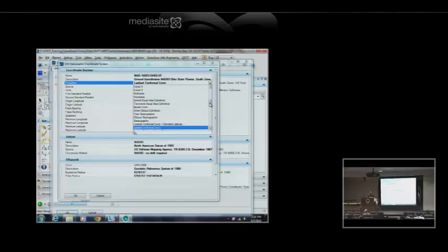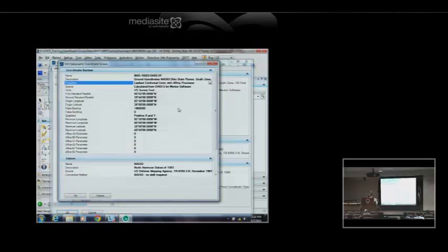All right, so there's the projection system. I'm going to change this to the Lambert conformal conic with an affine post-processor. There's Bentley documentation for all this stuff. This is what allows me to define scale factor parameters. So I don't have the correct scale factor for this project and make something up. So it's defined in two of the parameters. And again, I have this documented in that training guide.